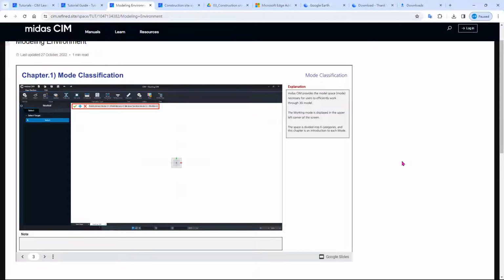So the first one is the point library. Point library is basically just a single model that usually will be merged together into a curve. So for example, the point library will be like a pier of a bridge, and maybe a girder of a bridge. And usually after you have created the point library, you can add all of the point libraries and you can assemble them into a curve library. So curve library is just like different point libraries that you assemble.